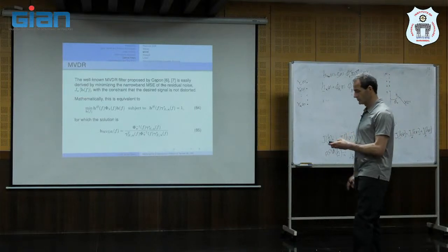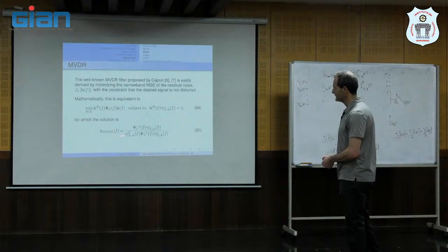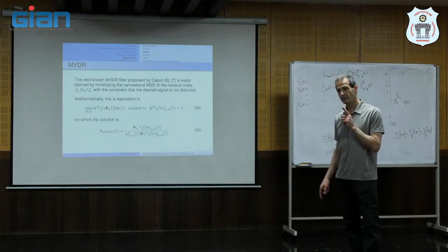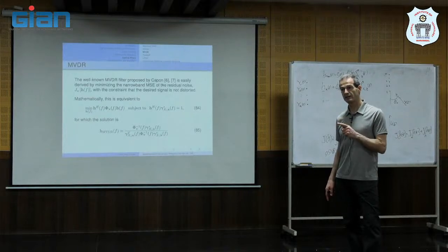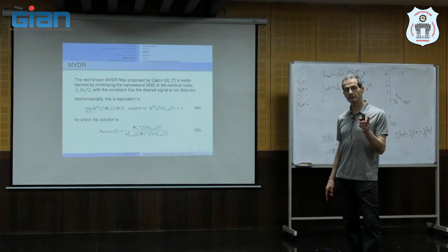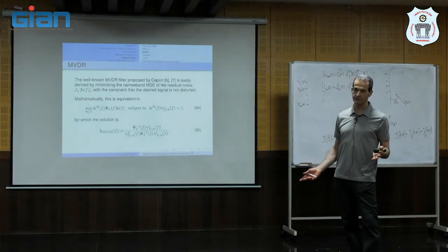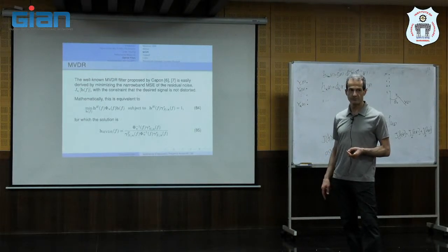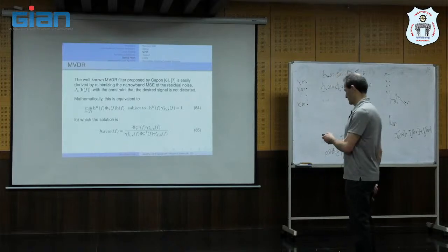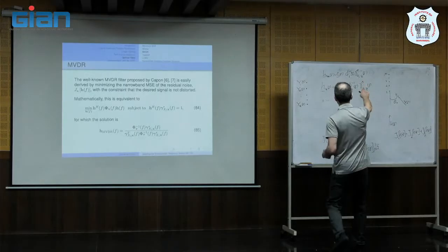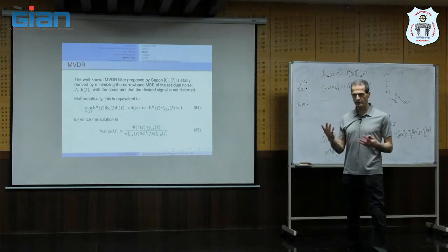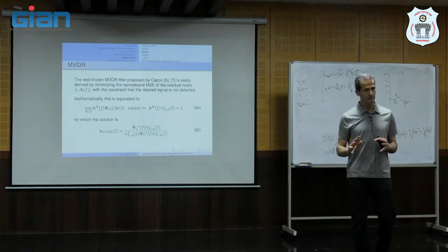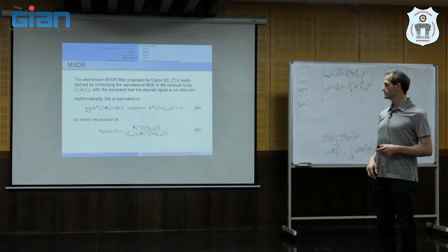If I ask you, we see the MVDR filter maximizes the narrowband output SNR. Does it maximize the broadband output SNR? Of course not. But it maximizes the narrowband. So it helps us to identify the differences between narrowband and broadband, which are very important.